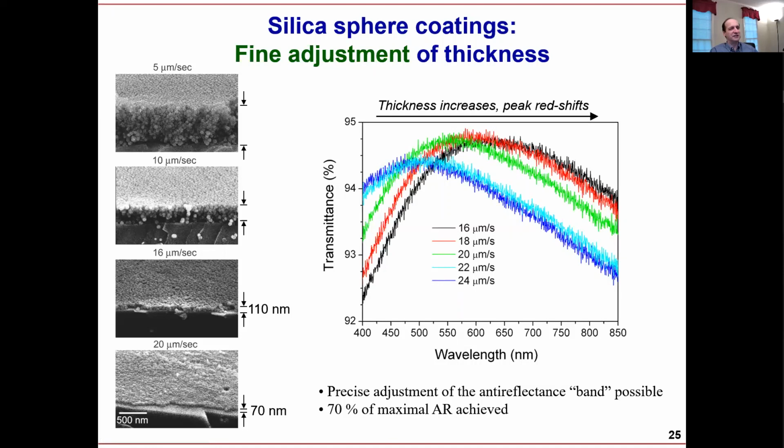Let's see whether you can match what we did at that time. Change the fluid. No, the fluid is evaporated, right? So you have particles, silica, deposit them, coating, liquid evaporates, you only have the silica layer behind. If you use this method, you can deposit a monolayer or thicker layers or a very thick layer. You can deposit a layer of any thickness, but it is going to be close packed, so your refractive index is going to be the refractive index of close packed silica particles. How do you control that refractive index?